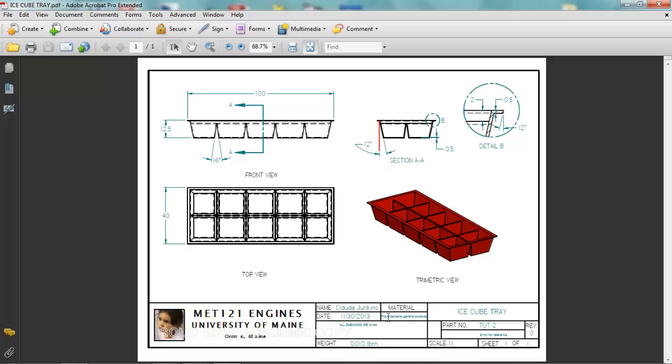It's going to be polypropylene material. I just assume that's something that's a flexible plastic. So it has these slopes, and it's going to use something called draft, which gives it its angled side, and we're going to use a thin shell operation and also a web network to create this object. So you'll see how this works as we put it together. I'll leave this open so we can refer back to it. You can see the initial shape is a 40 by 100. It's actually going to be 14 millimeters deep to start with.